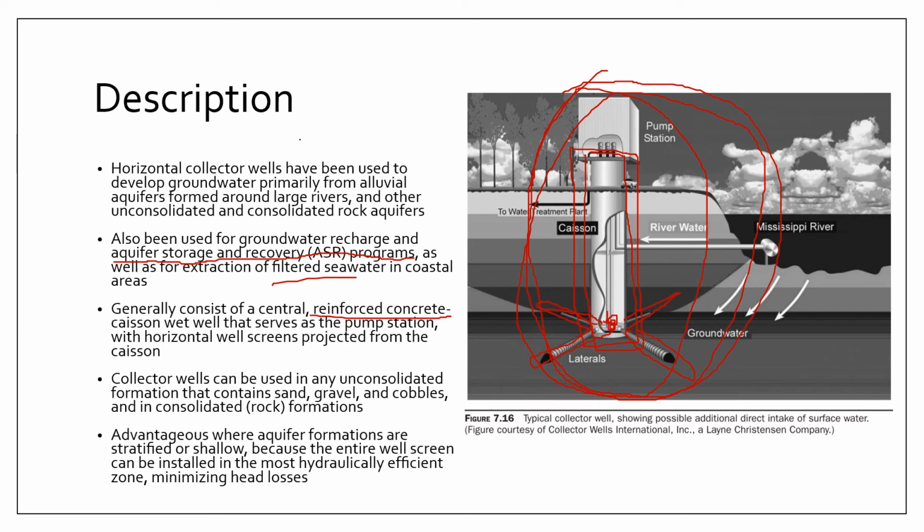All right. The advantages of collector wells, of course, include situations where your aquifer formations are stratified. So when the formation is stratified, you can easily select, or easily target certain layers for extraction. And of course, in terms of hydraulic efficiency, you can easily design the well to ensure that the hydraulic gradients are optimal.